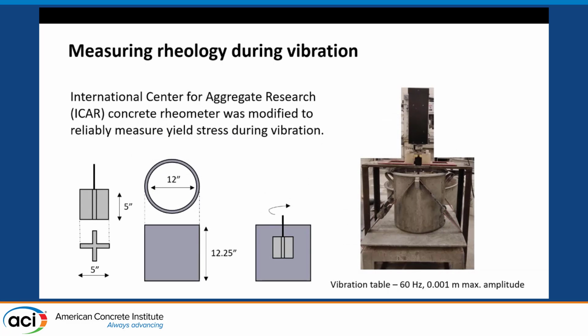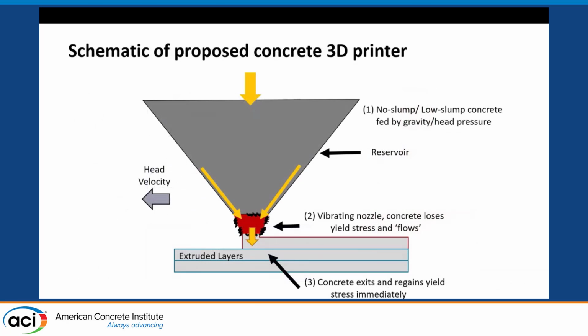But there is no reliable way to measure rheology of concrete when it is being vibrated. So what I did was modify an existing concrete rheometer by basically placing it on a vibration table and carrying out rheological measurements when the vibration table is vibrating.